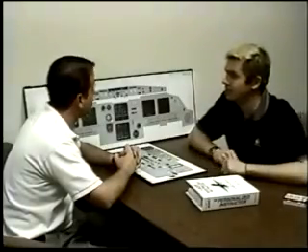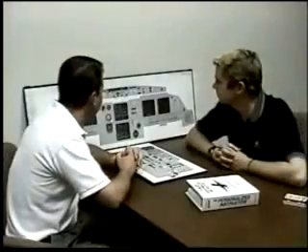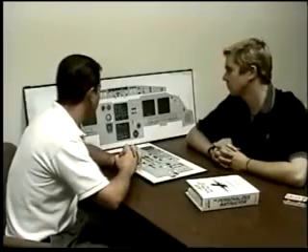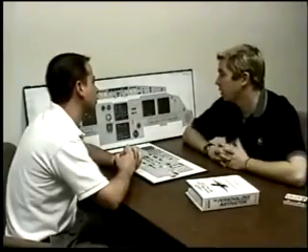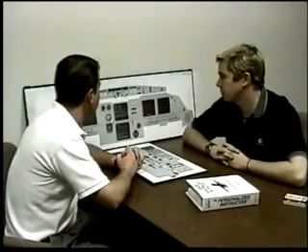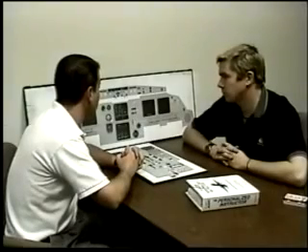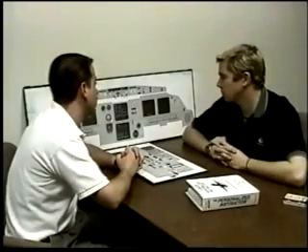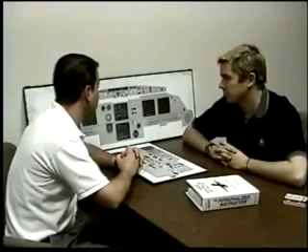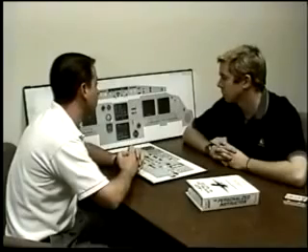Flight attendant corner pocket. Normal brakes is done through the green hydraulic system. What would occur if you lost green hydraulic system? I'd lose normal brakes. Okay. You've lost green hydraulic system. The BSCUs are still working, so that should force you into alternate brakes. Correct. BSCU, brake steering control unit, provided you had that still available, you should still have anti-skid.